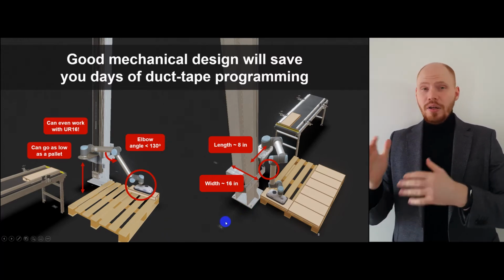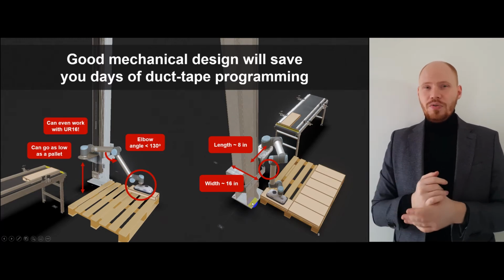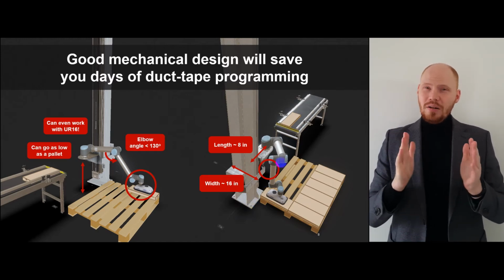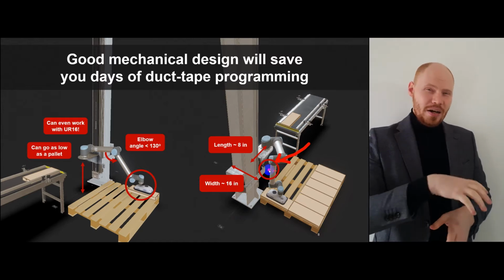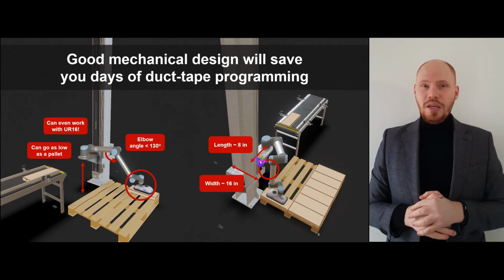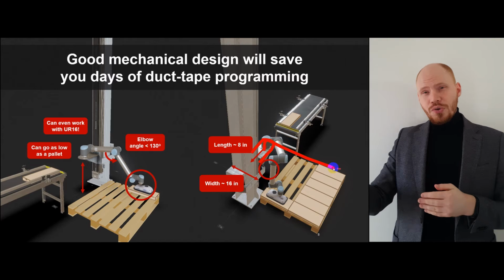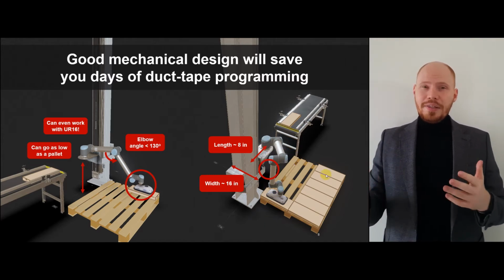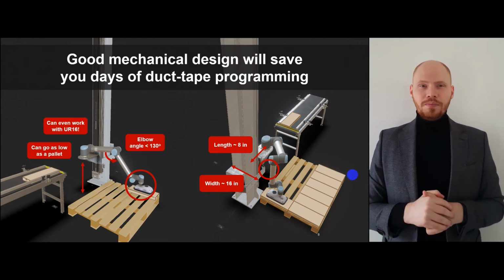On another hand, if you want to find a balance between the column stability and workspace restrictions, as a rule of thumb, you want to keep the width of your column reasonable to avoid joint collisions when placing boxes behind the rail. Similar rule applies to the length of the guide car. You want to keep it long enough so the robot can reach all corners without joint rail collisions, and at the same time it needs to be short enough to avoid bending too much.